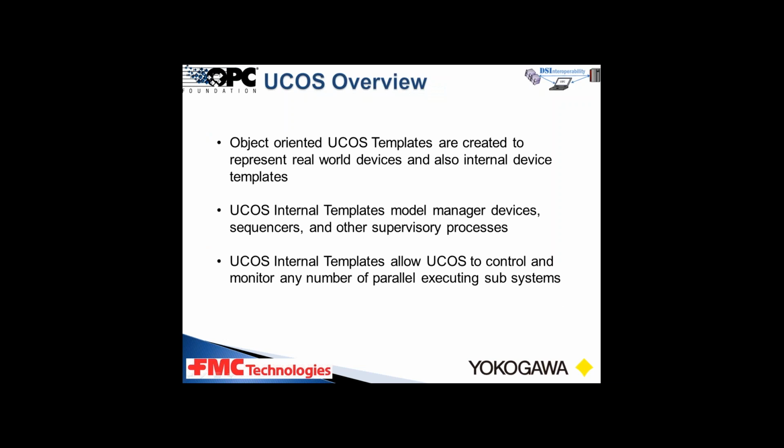So again, these object-oriented UCOS templates are created to represent real-world devices or internal devices. In other words, you might create a template to represent a real-world valve, or you might create one to represent something more virtual, like a shutdown sequence. In this case, for MDIS, we created templates that represent overlays on real-world devices in our system. UCOS internal templates can be used, again, to model connections to external subsystems and other high-level process control algorithms.